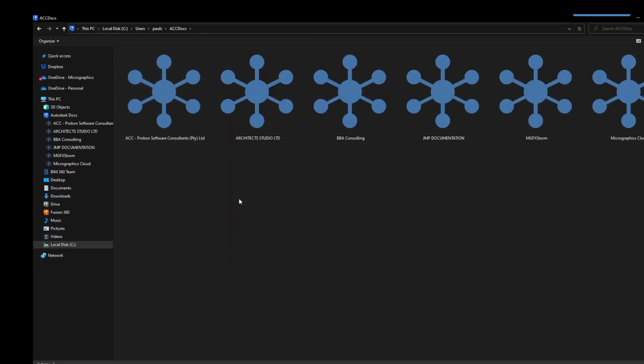Now this is important to realize because we've got the first part of the file name there. Just note that whatever path is on our computer is synchronizing via C drive, Users, and then the username. And for those of you that are familiar with Revit files, you'll know that your username identifies you uniquely. And if you don't have a common drive network path for Revit files, it will fail.